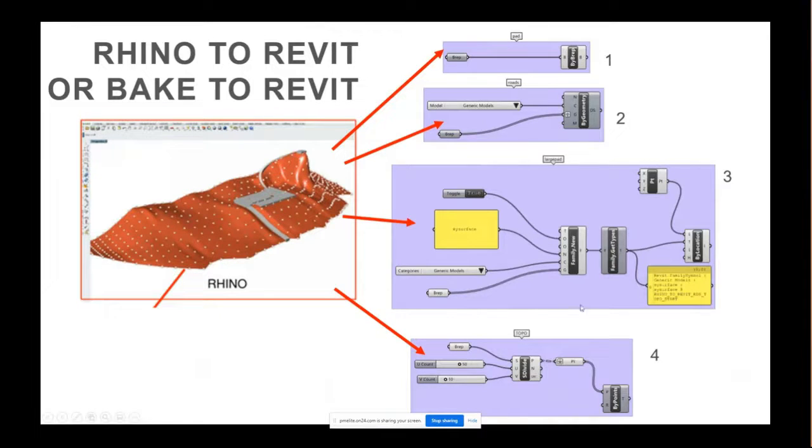Now, you're looking at Grasshopper nodes, and these are just simple examples. I also want to mention that you don't have to bring in your entire Rhino model. In fact, that's probably not advisable. You take the whole Rhino model and shove it into Revit. You need to make decisions for each element that is inside of Rhino, because you may not want to bring everything in, right? And we can get into that a little bit later. But these are decisions that you definitely need to make.